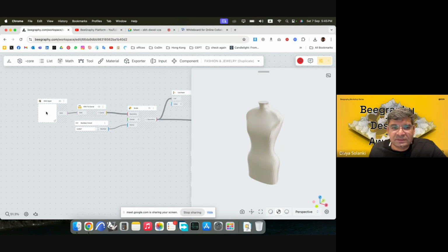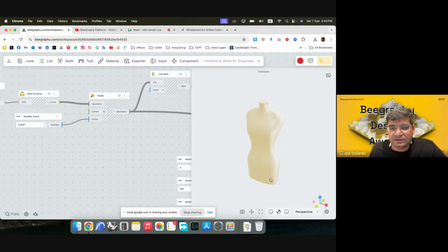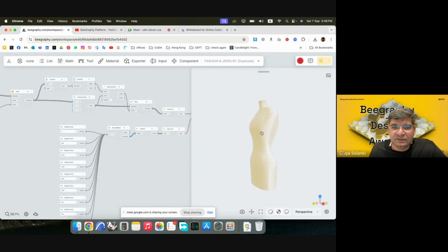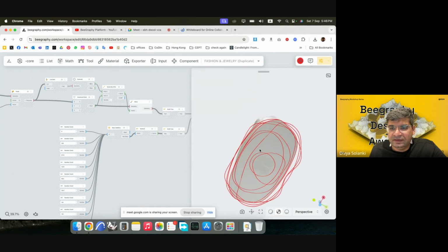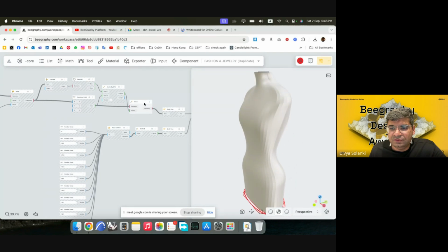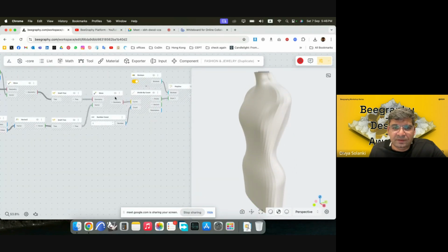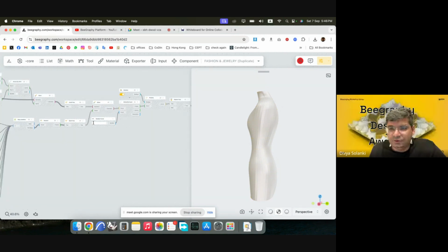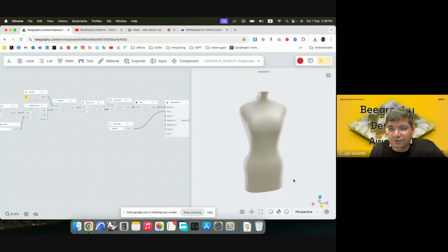So how I did this was I just got in some reference curves which were based on the sizing of different parts of the body, wherever the contour of the body was changing, and then these were put to scale and then moved to a certain height. So for instance, I got the SVG file in a two-dimensional fashion, and then I moved them up to their individual locations, and then I just lofted them to generate the final form.